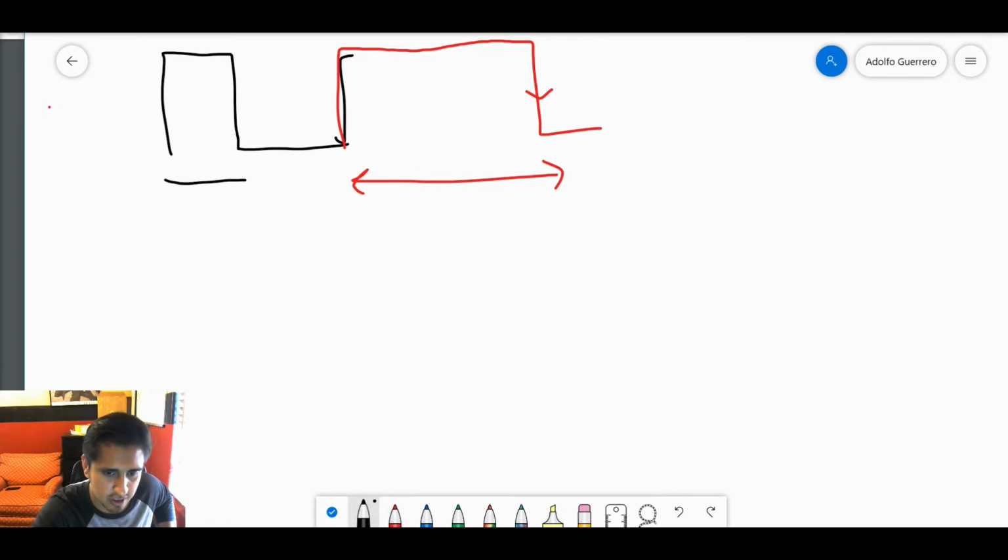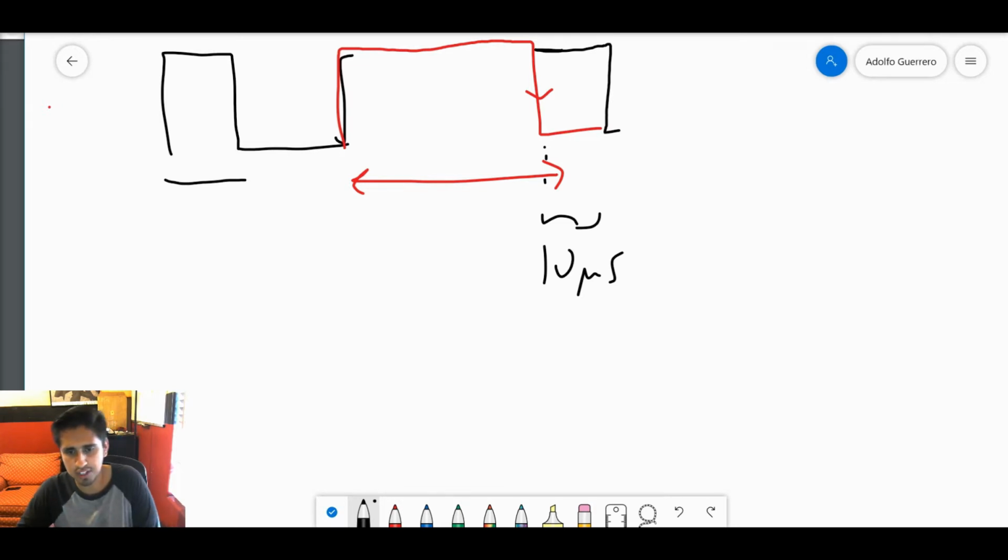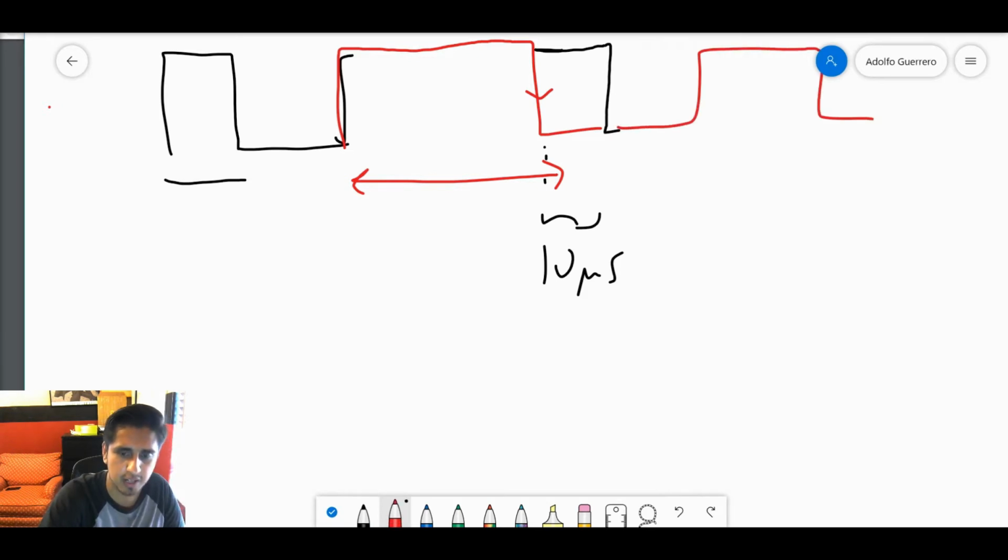After this we set the pin high again, and then we sustain that for 10 microseconds again, and we utilize the same one-shot timer to tell us when 10 microseconds have passed, so that at that same interrupt service routine we would repeat the same process. We set that pin to low again, and then we get ready for edge detection again. And then we repeat that process indefinitely.